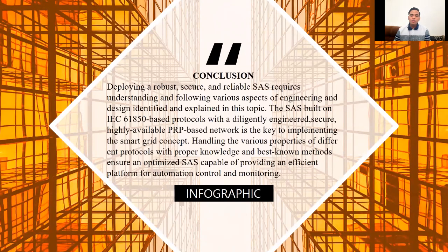So in conclusion, deploying a robust, secure, and reliable SAS requires understanding and following various aspects of engineering and design, identified and explained in this topic. The SAS or Substation Automation System built on IEC 61850 based protocol with a diligently engineered, secure, highly available PRP-based network is the key to implementing the smart grid concept.